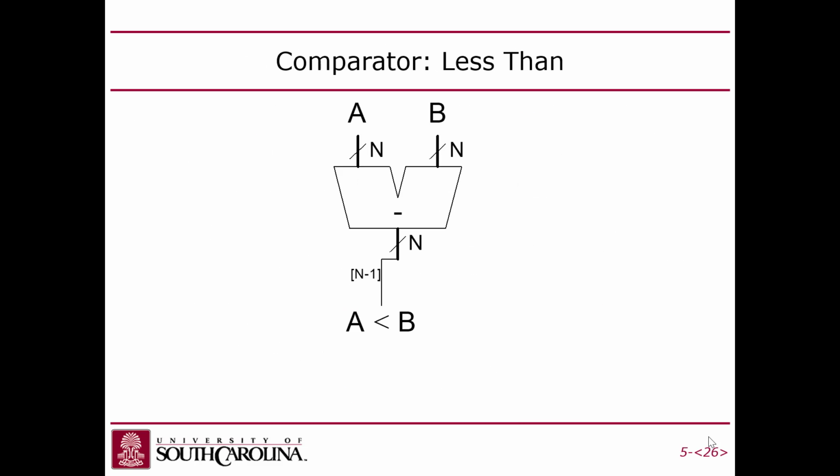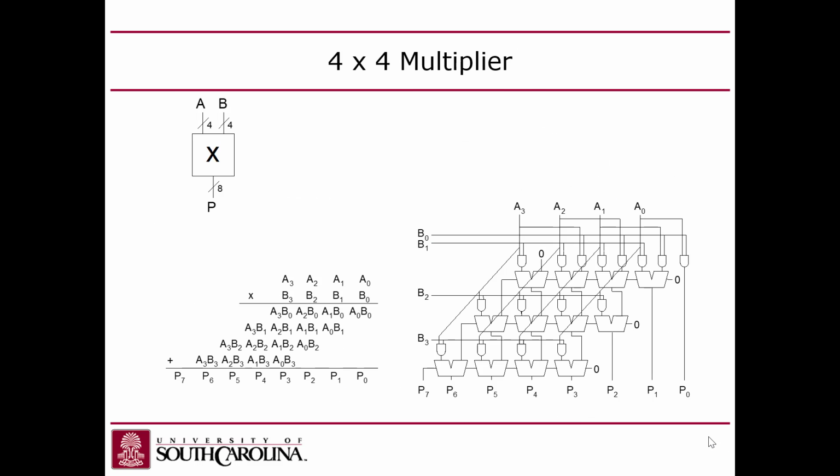So with the multiplier, you can take each bit of A, which is the multiplicand. B is the multiplier, right? And so because B is the multiplier, notice that B is being used to gate the first stage of A. When I say gate, it's like putting them into an AND gate.